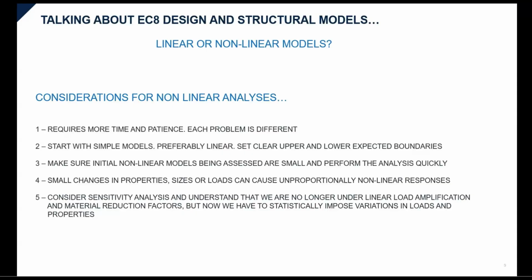Keep in mind that small changes in properties, dimensions, or loads can generate disproportionate results, an example being nonlinear responses. And on the other hand, it is important to consider that we must always perform a sensitivity analysis and understand that we are no longer within the concept of linear amplification of load factors through load combinations and partial factors. It is now our responsibility to determine the statistical uncertainty of which types of variables and loads we must define.